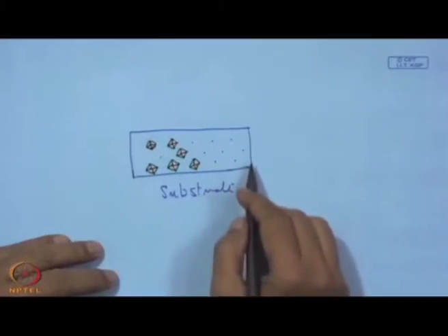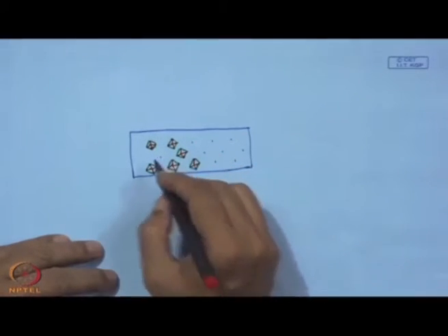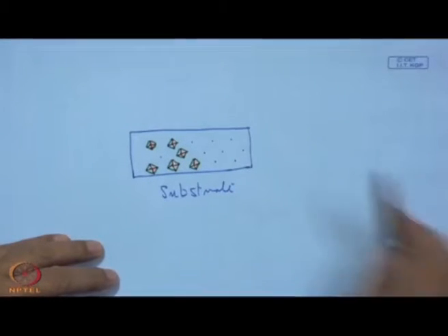From a chemistry point of view, it should be a carbide former, and it should have very close matching of thermal coefficient of expansion, the E value should not vary too much. If we can satisfy those things, then it will be another promising technology using this CVD process, but not for getting a continuous coating, rather a coating over this substrate surface with selective growth.